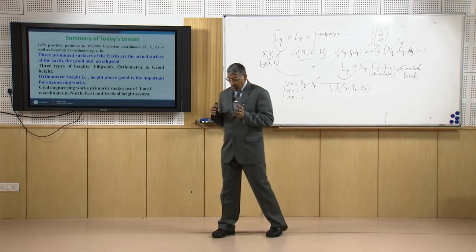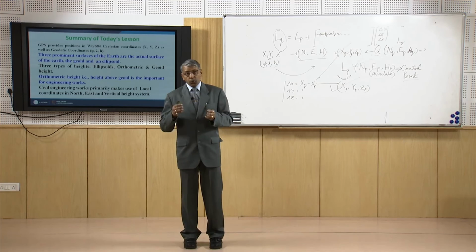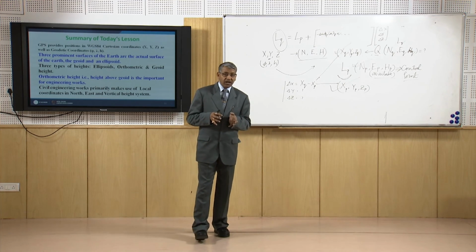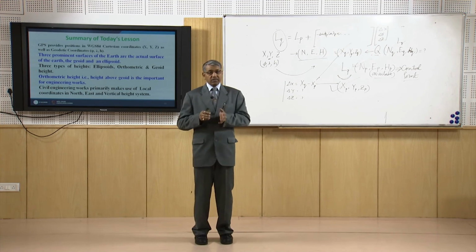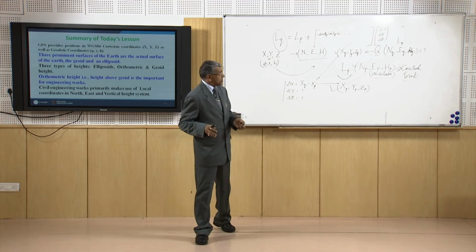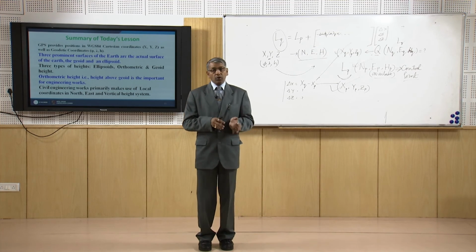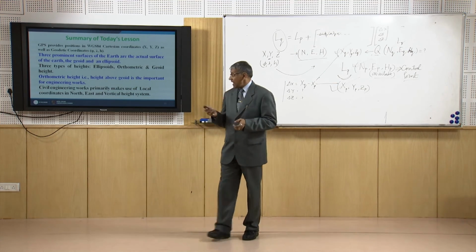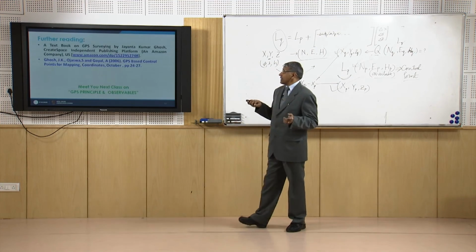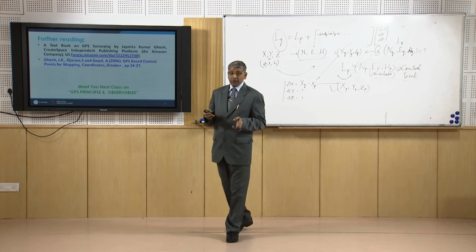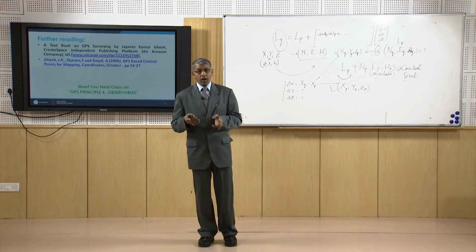And for all our engineering works, we actually need to have the local coordinates in terms of north, east and orthometric height, which we can get from GPS coordinates through conversion. With this I would like to conclude, and in the next class I will be talking on GPS principles and observables.